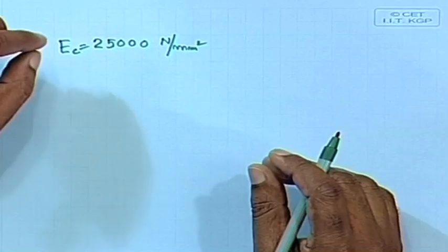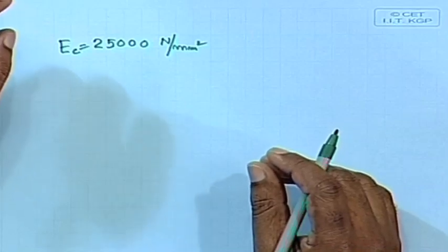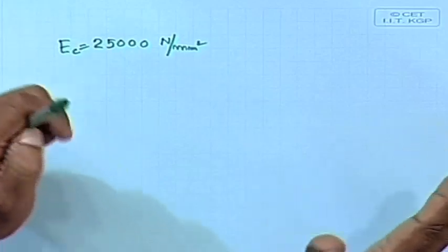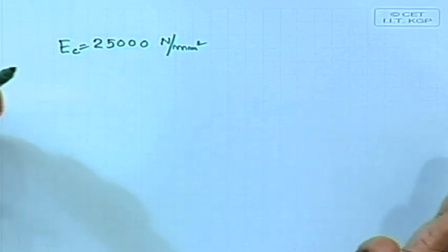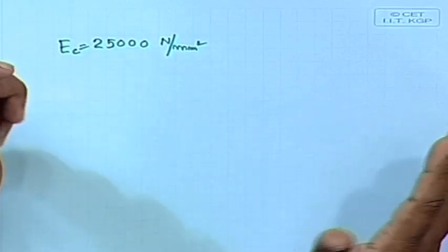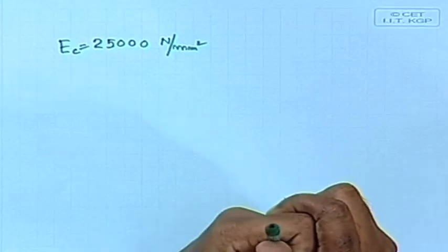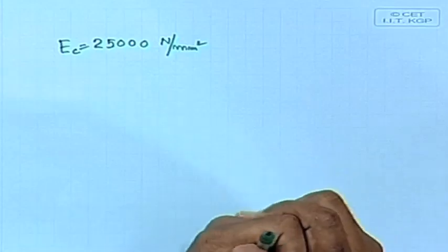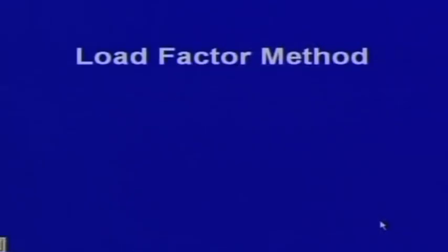This is because of shrinkage and creep, because it is a time dependent phenomenon that concrete exhibits. Because of that the modulus of elasticity changes, particularly because of creep and shrinkage, so we cannot get a definite value. The one we can get is for steel. We shall come back again to that working stress method with a small problem.